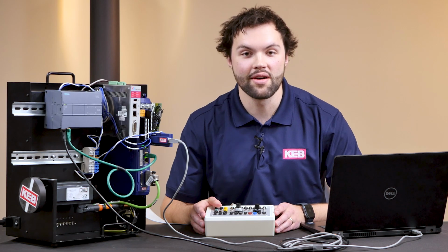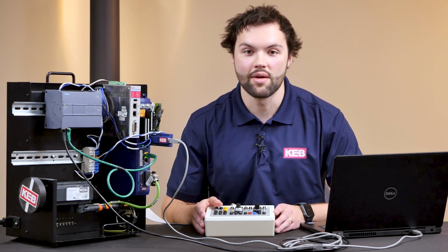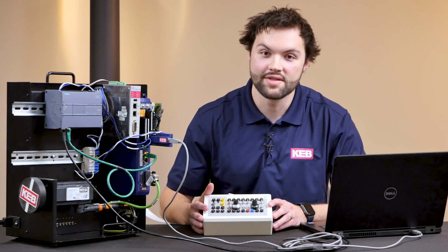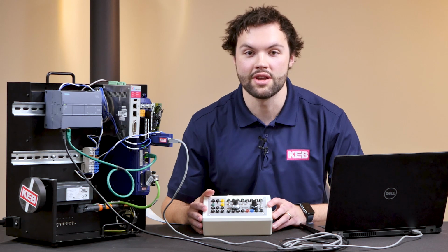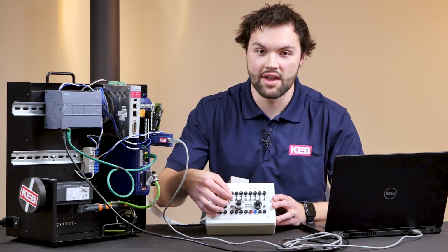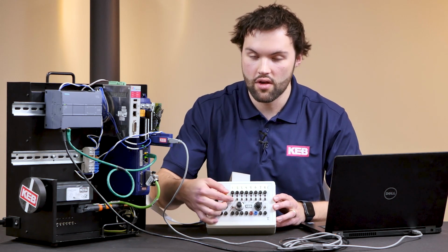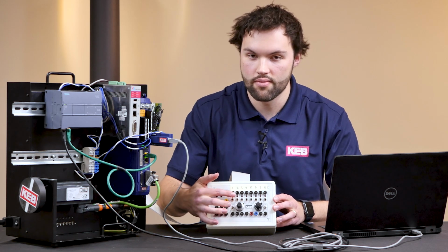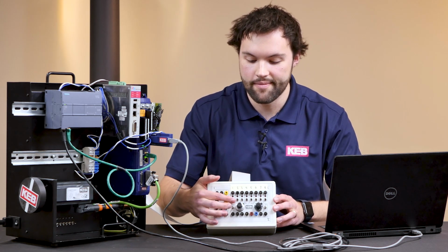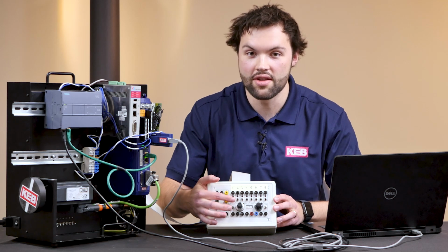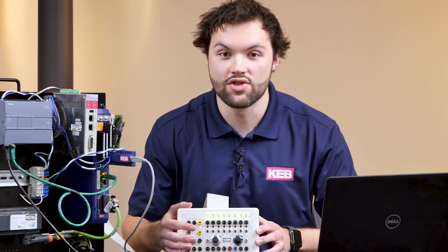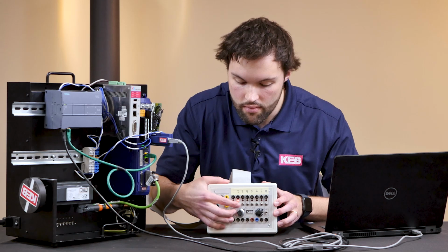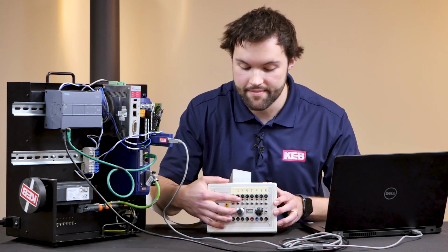Now that everything is set up, let's see our motor spin with our demo. So again, the state machine is controlled by digital input 1, which steps through each state. We will start at state 1, go to state 2, state 3, and then finally our enable operation state, state 5. If we want to stop, we can just trigger digital input 2, and the motor stops.